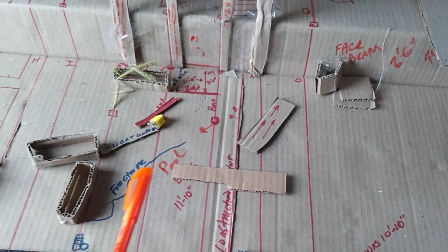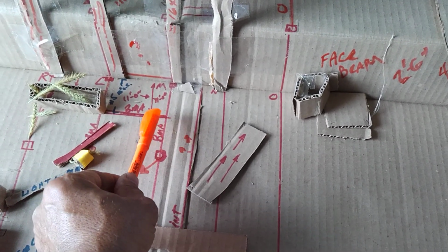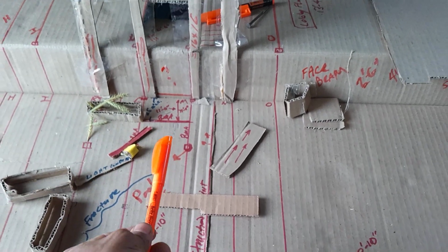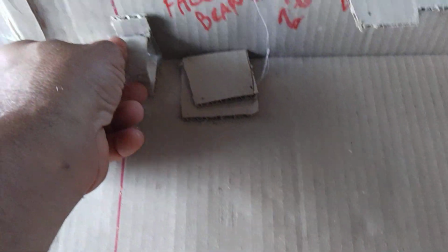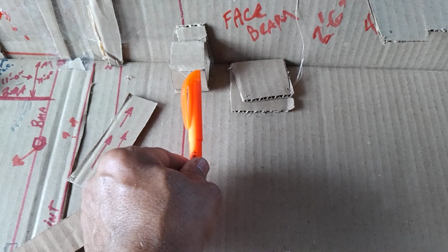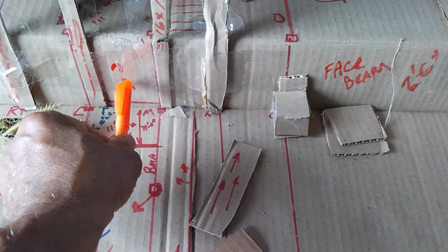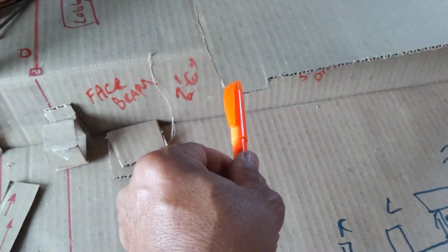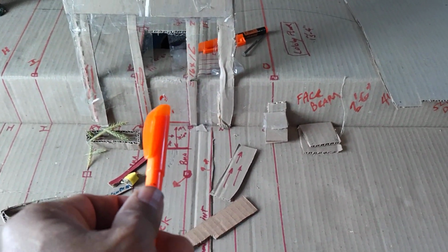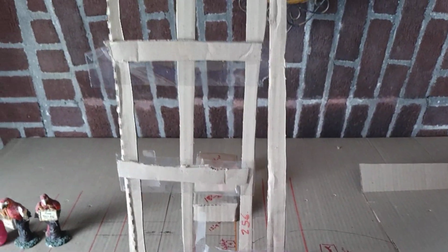So as we get this deck failing out here, we can get our crazy torque action going on. We have multiple elevations. So as it's pulling up on a ramp, if you will, it's pulling up on an elevated deck. Pulling from here, pulling up on an elevated deck, changes the moment of its reaction where it's pulling. And remember, this is not 2'6", this is now 1'6". So now we're getting closer to pulling at the top there. And remember, when we pull at the top, we start this bad boy shaking, rattling.